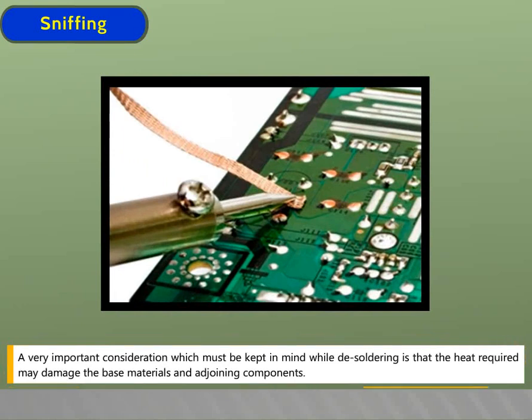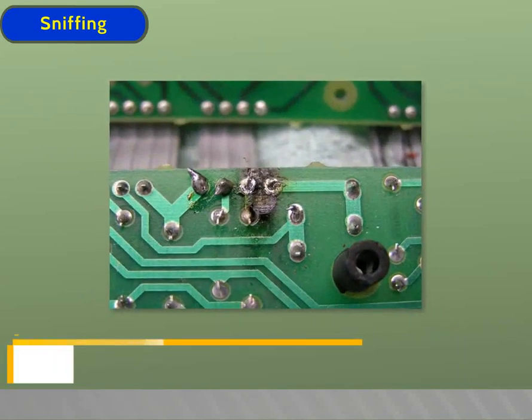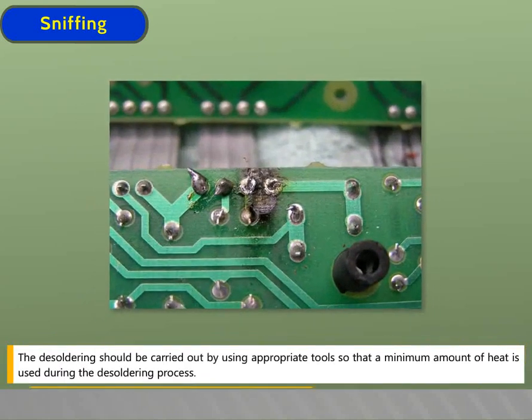A very important consideration which must be kept in mind while desoldering is that the heat required may damage the base materials and adjoining components. The desoldering should be carried out by using appropriate tools so that a minimum amount of heat is used during the desoldering process.